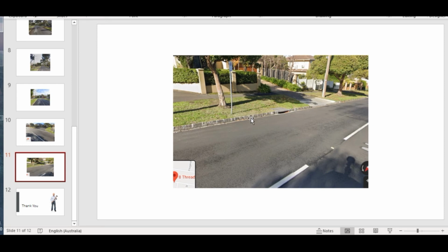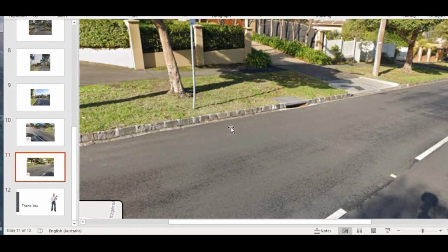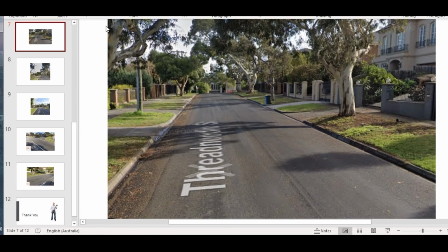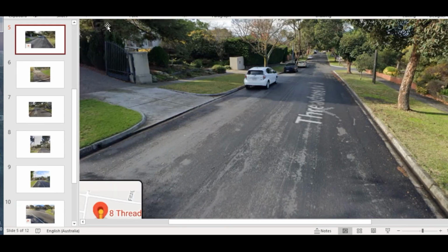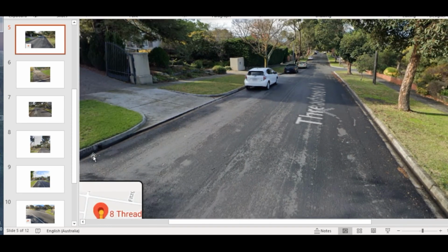The downpipe might be connected into the road. From that point of connection, as you can see here, if I zoom in, there is no downpipe connection here. I can find some other figure. As you can see here, from this property the water falls in here, and then it gets into the kerb gutter lip. All the way it falls down the lip and goes to the nearest lintel or inlet. So again, we calculate that property water flow as well to be able to optimize the design.